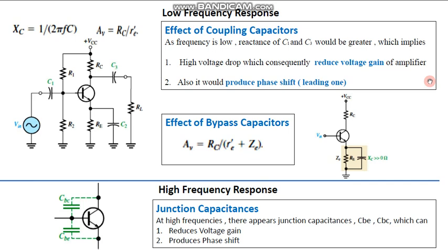Okay, let's finish the high frequency effect, the phenomena of high frequency on this amplifier. So basically we can say that when the frequency of the signal, this f, increases, by this relation, when f increases, your Xc would go down, it decreases. So when Xc decreases, you can see the C1 over here, this C1 can be effectively Xc, when it decreases, we can assume this to be 0.